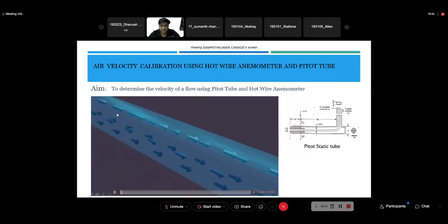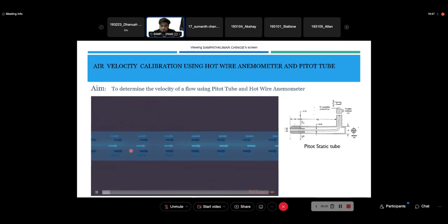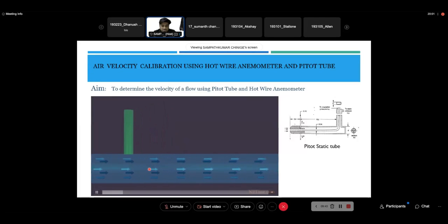So now you could see here there is some velocity through the pipeline. So we are seeing some flow happening over here. At any location, the particle consists of some energy, right? That energy we call stagnation pressure. When it is at a standard condition, the total energy is nothing but its stagnation pressure. Now when it is flowing over here, if you put a piezometer like this, some of the liquid will rise over here. That means when it is at static condition, the energy it has is basically your static pressure.